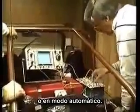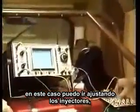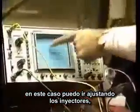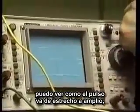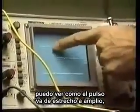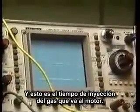And in this case, you notice how I can adjust the injectors. See how the pulse is going smaller and then larger? I'll bring it over here, you can see it. There it's going smaller and then larger. And that's controlling the inject time of the gas going into the engine.